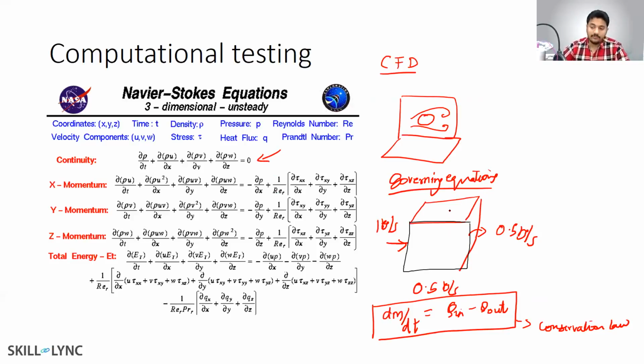Similarly, when you take this 6-faced control volume, and if you balance force, then that's where you get the momentum equation. Now remember, force is a vector quantity. It has 3 components. So this is Fx, Fy, and Fz, right? And these are your governing equations. These are partial differential equations, which basically say, hey, these are the rules that your fluid should never disobey. And finally, you have your energy equation, which is a scalar equation.